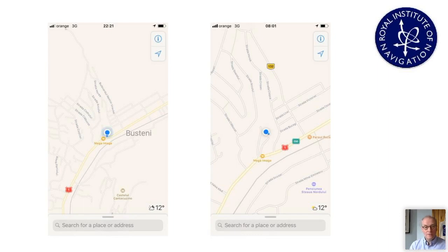And the DOP, if you watched the first talk we gave last week, dilution of precision, was higher, and hence you can multiply the DOP by the accuracy. If the DOP was 2, for example, the accuracy would be half as good. But both of these are examples of position fixes using the satellite navigation sensors in the smartphone.